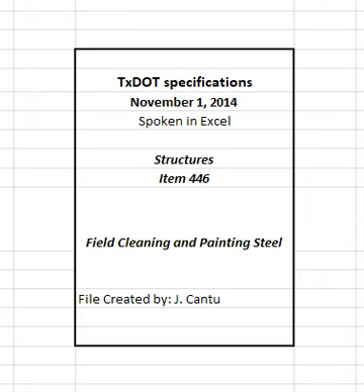Do not damage adjacent materials such as concrete during surface preparation or painting. Feather all sound, tightly adhered coating edges surrounding cleaned or repaired areas a minimum of 1 inch and ensure a smooth, blended transition. Round all corners and edges to a 1/16 inch radius. Reblast as needed. Remove pack rust to a depth of at least 0.5 inches.